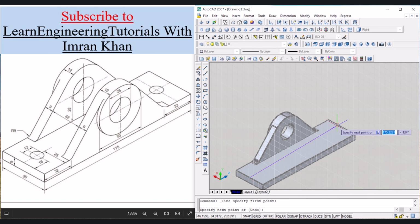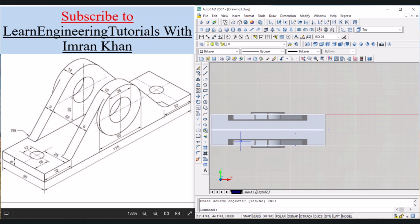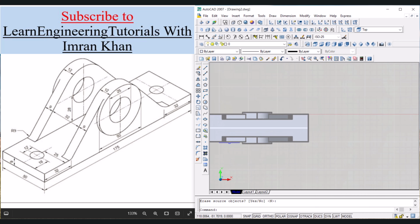Now we want to mirror this object to this side. For that we will use top view, and now we can select this object, click on mirror, select this point, then this point, erase source object no, press enter, and now we can see that the object has been mirrored. Remove this line, press delete. Now what we have to do is to draw these circles.